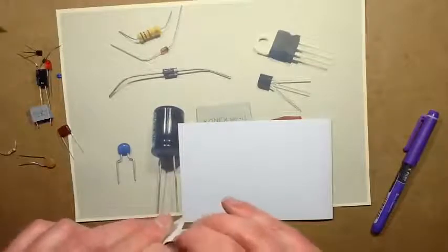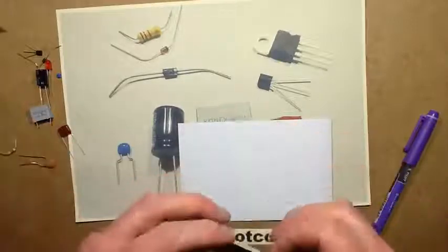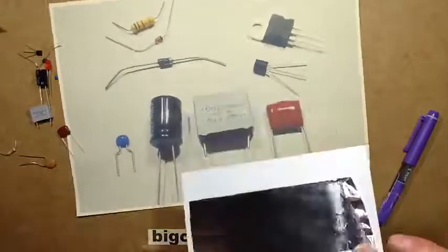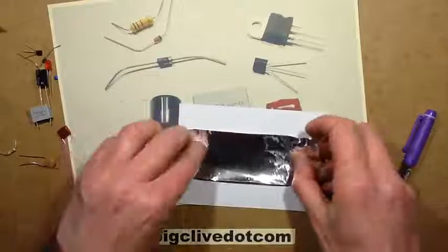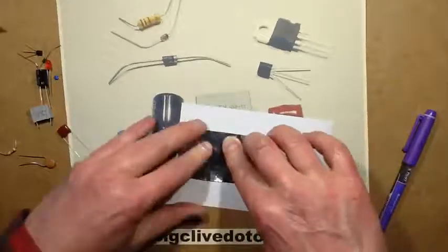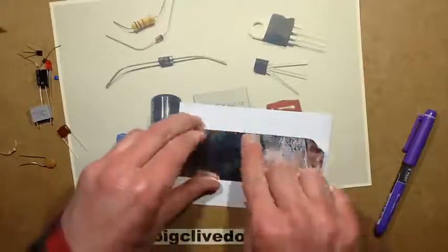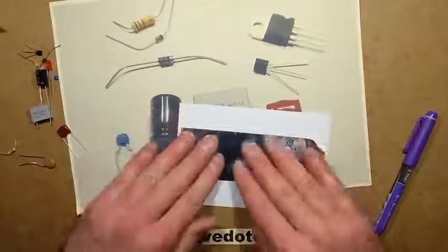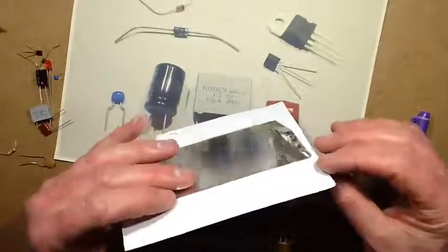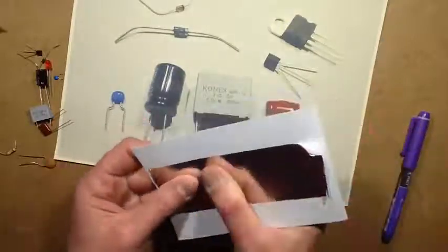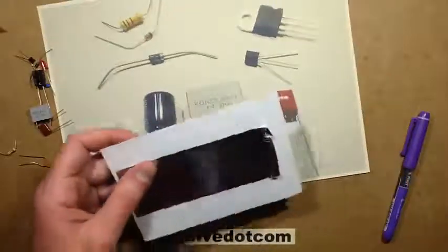And this is the physical construction that's used throughout all capacitors. They're all pretty much like this, but not using cardboard and aluminium foil. So let's get that as close to the other one in alignment as possible. And the 2 factors determining the capacitance here are the area of metallization that's in parallel with the other one, and how thick the insulator is in between. And you'd think, this card is very thin, so it's going to be a modestly high value of capacitance, but that's not true. This is not going to be a high value of capacitance at all.